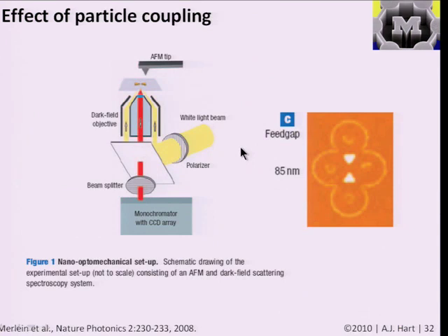And another thing of interest, as we saw in the case of the nanosphere lithography process, is that the position of the peak or the spectrum is also very sensitive to the spacing between objects, because the fields that are created in one particle can interact with the fields that are created in another particle. So it's challenging, or pushing the limits of fabrication, to make one of these metal structures with a precision of a few nanometers. And we'll get more numerical bounds for size control later on. But you could say it's challenging to control and know the size of this island with nanometer precision.